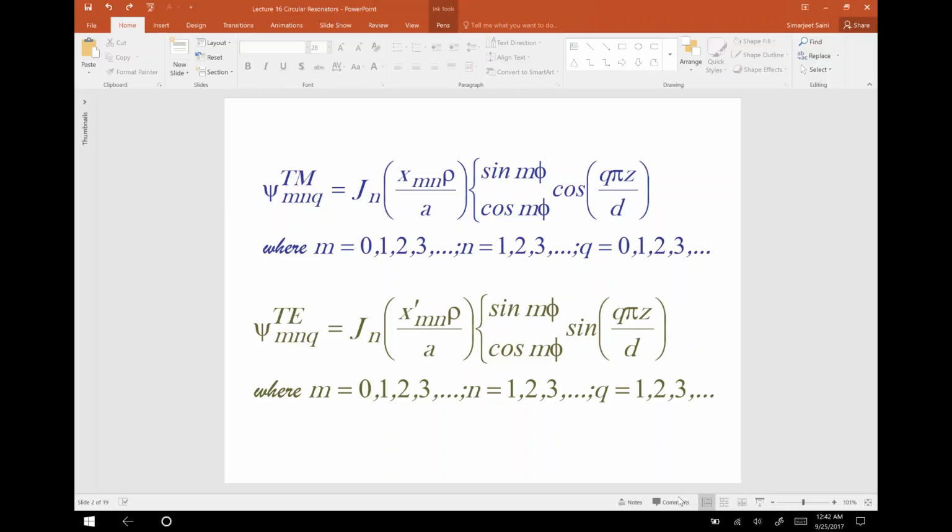Because there's no current flowing from the top to the sides, you can actually make a tunable frequency resonator by moving one of the conductors up or down if we use the specific mode. Do you have any questions on this?